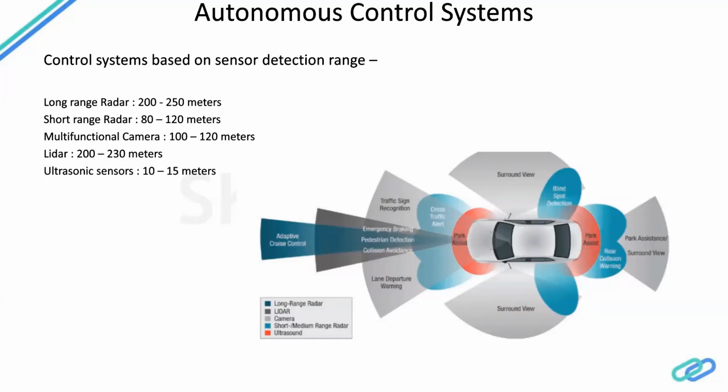So camera comes in handy in those kinds of situations to detect any false negative, whether the object is present there or not. So this is why camera is so mandatory nowadays for the systems that take care of adaptive cruise control or emergency braking, to avoid false braking or false accelerations.